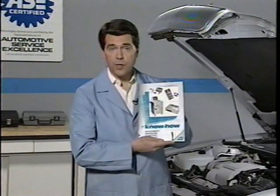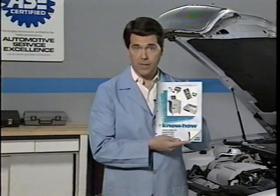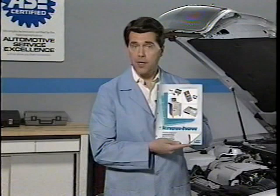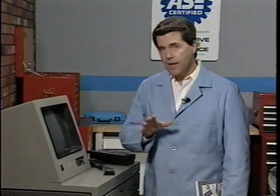Two releases in this series were, of course, on using scan tools to better read the ECM-PCM data stream when diagnosing drivability complaints, particularly when the problem we're trying to find is intermittent. But if we stop to think a minute, hopefully none of us grabs a T100 or Tech 1 ALDL lead right off when we begin the process of trying to solve a drivability complaint unless the vehicle is displaying a solid service engine soon light.